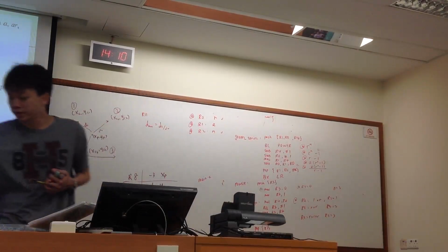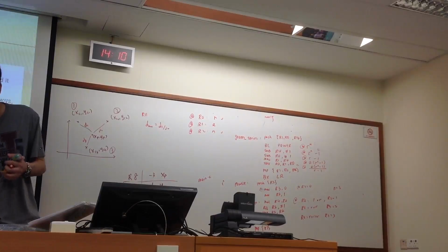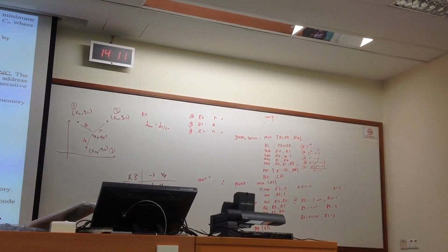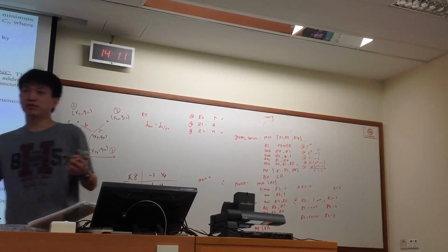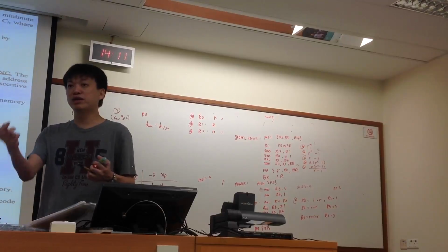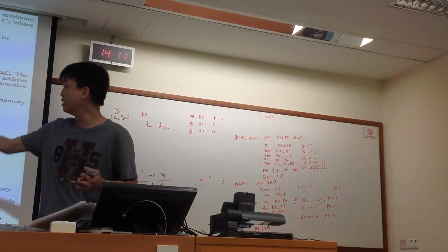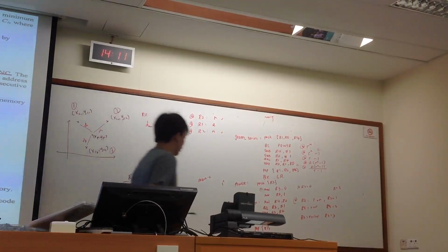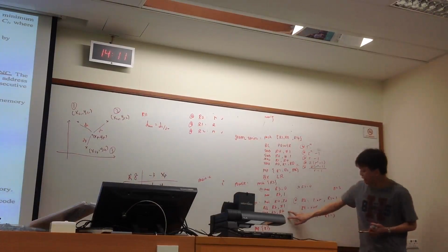It's just like the question just now, you can look at it, I think actually they provide the table. I didn't include it in that question. They check the Z flag, the zero flag. So even if you're negative, you also won't trigger the Z flag. You only trigger the negative flag and they will ignore it. Okay. So it doesn't matter R2. But how you select this one,